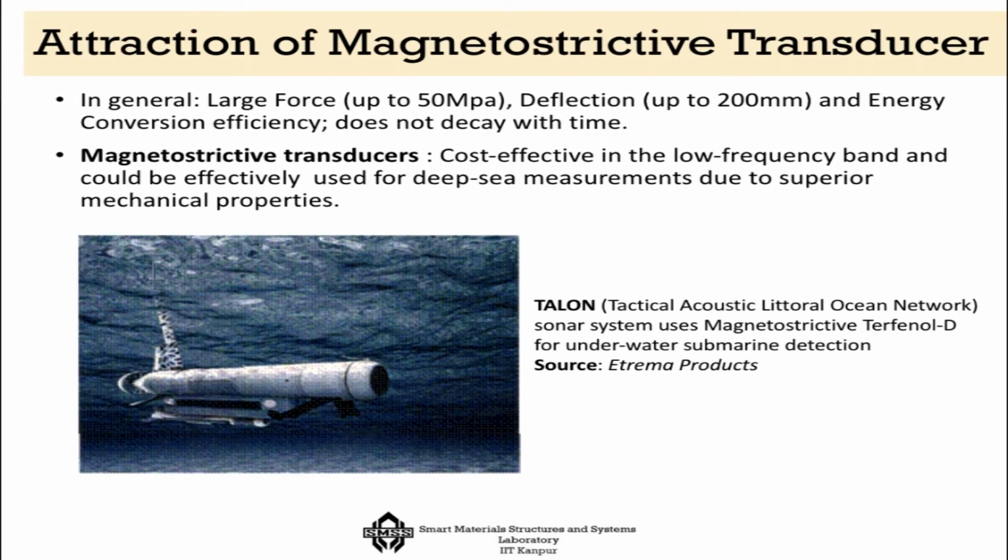Terfenol-D. Now the attraction of such Terfenol-D materials is manifold. For example, you can use it for large force generation, up to 50 megapascal stress level you can create. You can create large deflection up to 200 millimeter, and you can get a large energy conversion efficiency, and most importantly it does not decay with time. That's a very good advantage of the magnetostrictive transducer, and it is cost effective in terms of a low frequency band. It's not as high as the frequency band of a piezoelectric material,